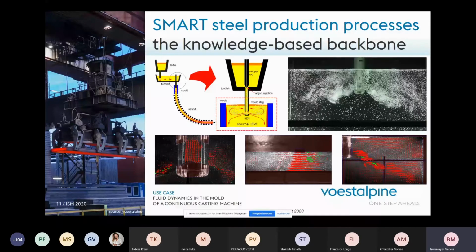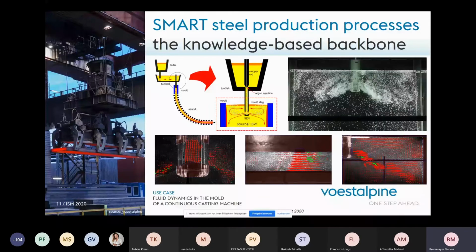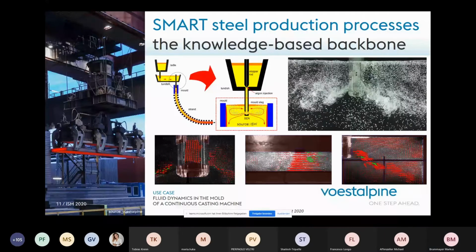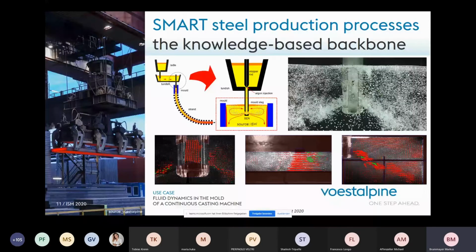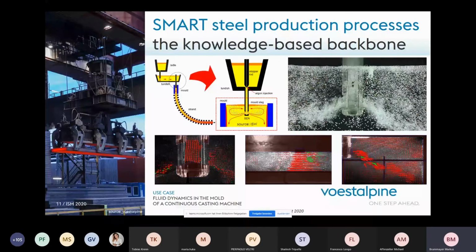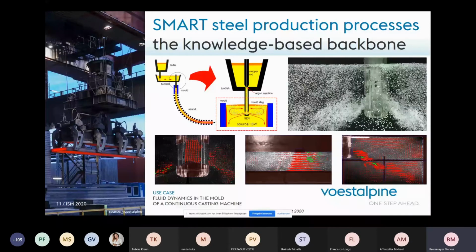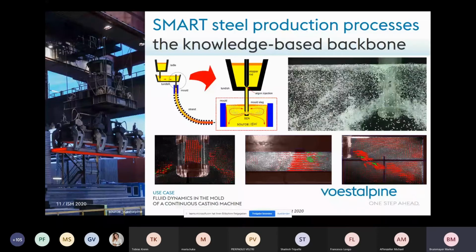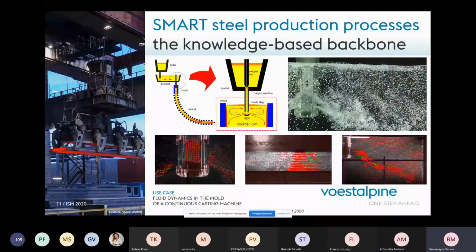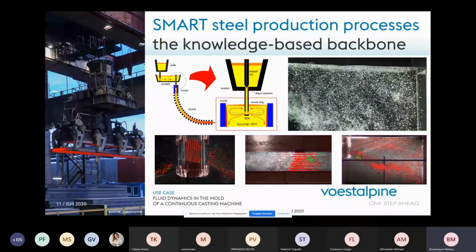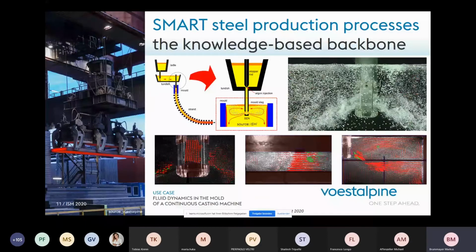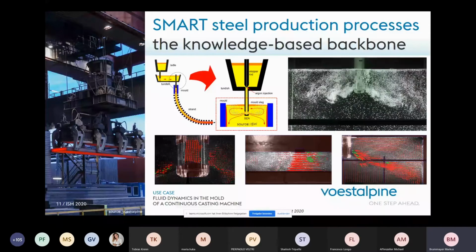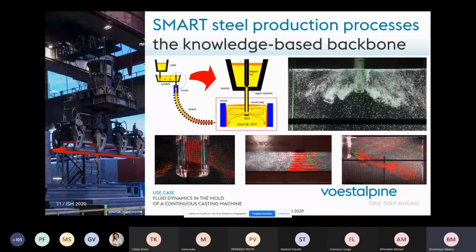And you can see these nice details that we are looking for, especially if you look at the meniscus. And you see the highly turbulent flow behavior. And we need full-scale water models where we get the Reynolds similarity and also the Froude similarity. And we can quantify these flow patterns with so-called particle image velocimetry. So on different slices, we can figure out and really squeeze out these velocity amplitudes and also the direction.